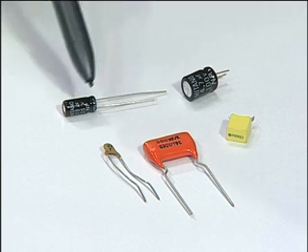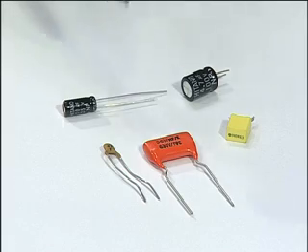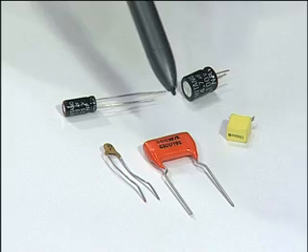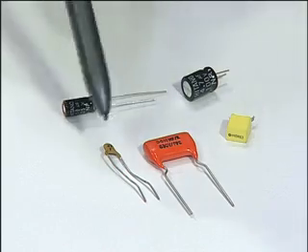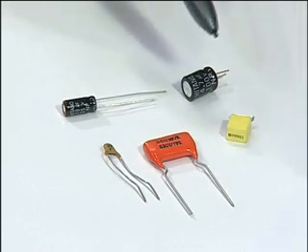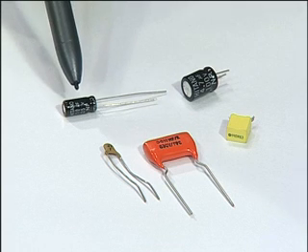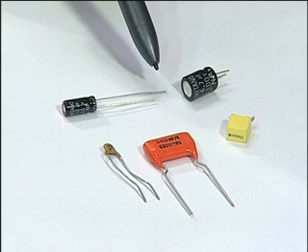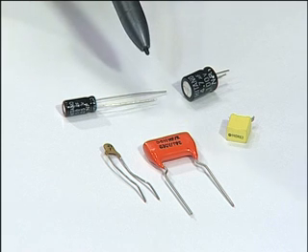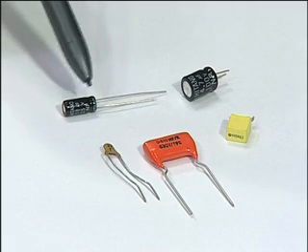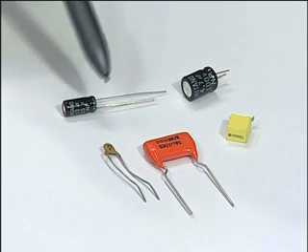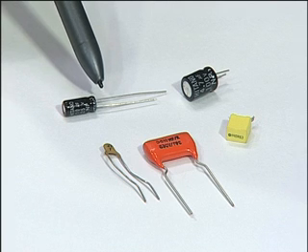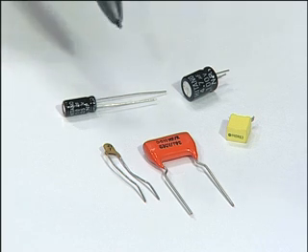So, these capacitors are in general used for actually holding the charges, whereas these capacitors also do the same function of holding the charges, but their application is more for frequency tuning, decoupling, things like that. So, this is aluminum electrolytic. You see there is one short lead and one long lead, that is to distinguish the positive and the negative pole. But even otherwise on the body of the capacitor there will be a plus or a minus sign put near one of the terminals to distinguish it from the other pole.